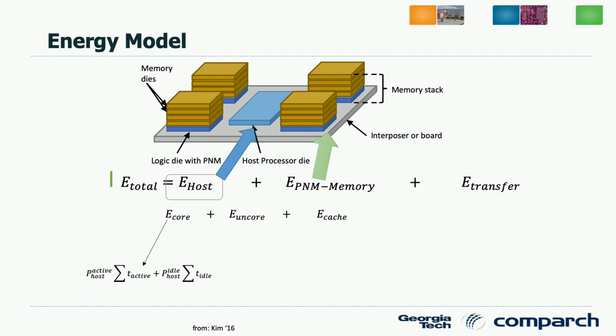When you offload to the PIM versus the host, we also need to consider the idle time, because if you offload some computation, the host can be idle. The on-core part is mainly the number of channels times the total time. Computer architects often mix up power and energy, but this really means energy, so everything needs to consider the time effect.